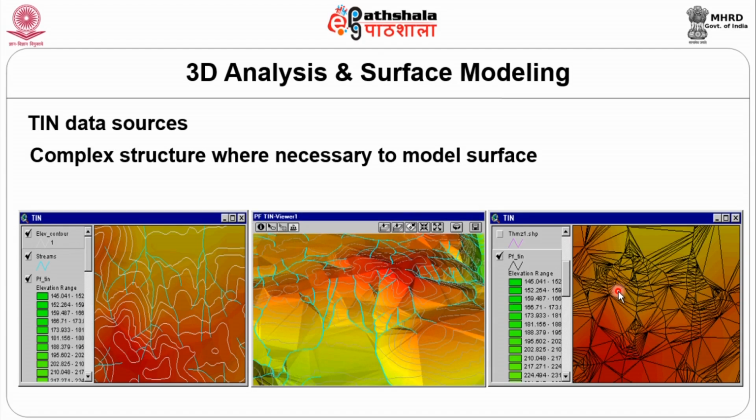You can see here when I zoom in on that area. From simple contour data and your drainage, which is already available from various sources, namely a topographic map or any other method of mapping, you create the TIN surface from this input and then generate a 3D model. Now, on viewing this, you will be in a position to see how complex it becomes. How do these water bodies, all these drainages, flow, from which direction to which other direction. This will be the demarcation, or the points of highest elevation, in a given terrain.